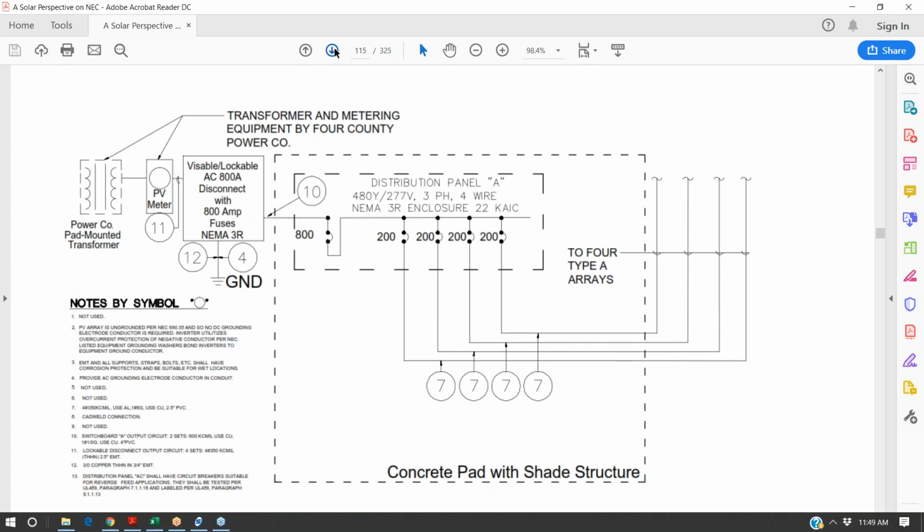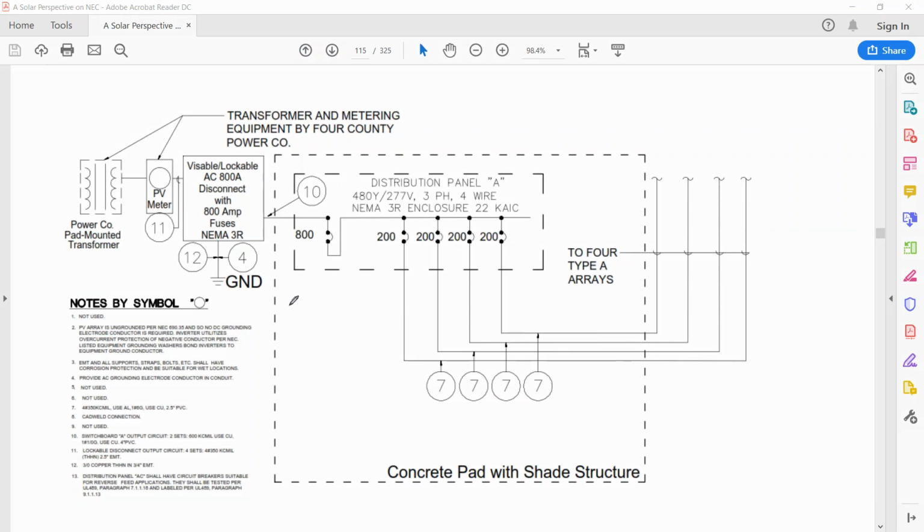I'll just share one on my own. I had a solar inverter where, here's our cable jacket and our little copper coming out of it. And what I had done is I stripped too much copper off. The copper was supposed to only be stripped off about a 1/4 inch, and I had stripped off a 1/2 inch.